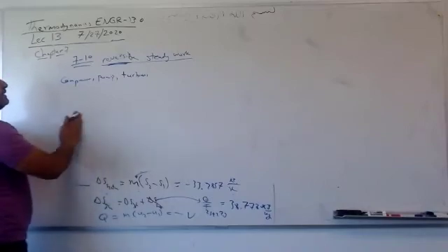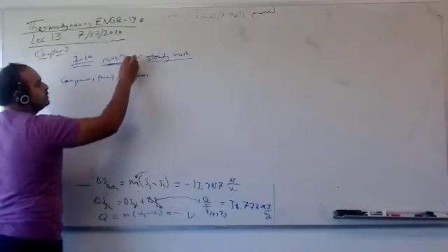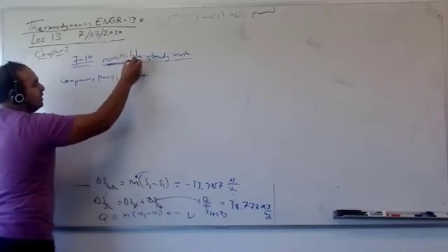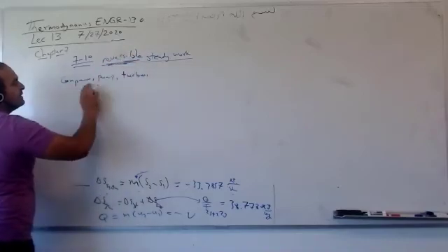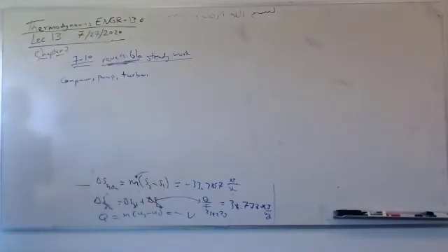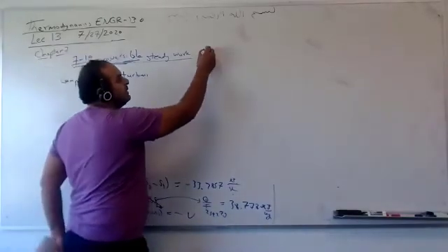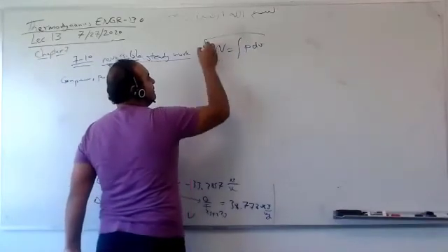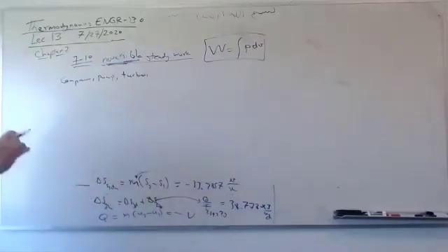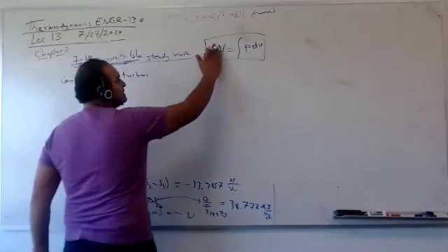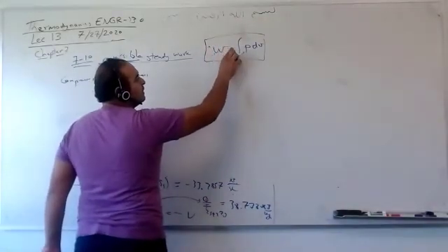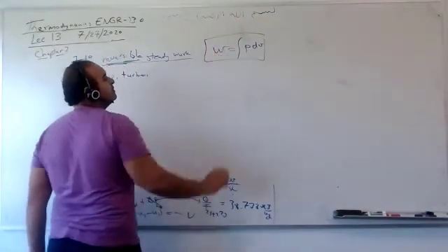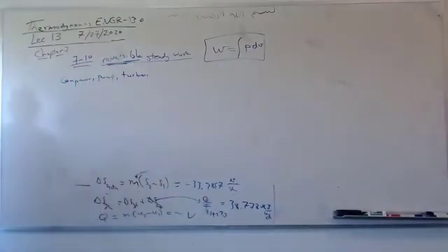For now, let's say they are reversible only. If you don't have heat loss, or at least reversible, you can say those. Generally, always correct: W is integration of PdV. That's always correct, reversible or irreversible. Area under the curve PV is the work. This is work per unit mass. If you multiply by mass flow rate, it will be power, W dot. Okay, guys?